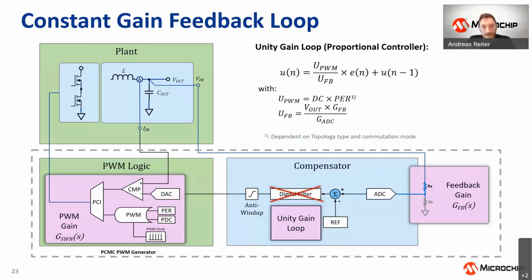When you change something, the loop is actually responding and trying to regulate the output, but in a very sloppy way with just a unity gain. It means every transient that's introduced will just pass through the system and show up at the output, and this is the system which gives us a good representation of the plant transfer function. So the additional constant gain we need to build into this unity gain loop is simply the ratio between output and input.